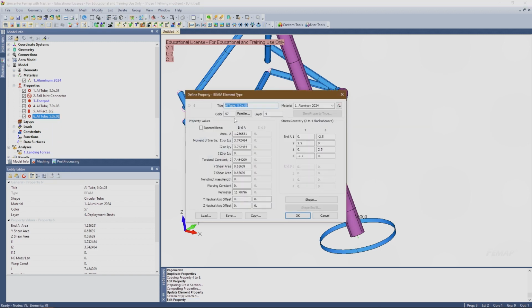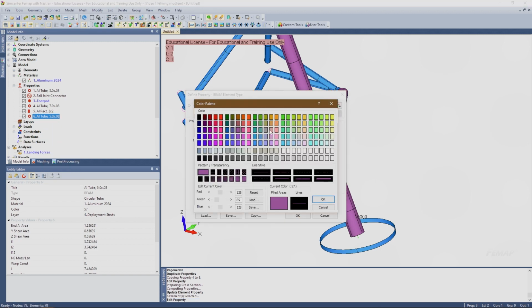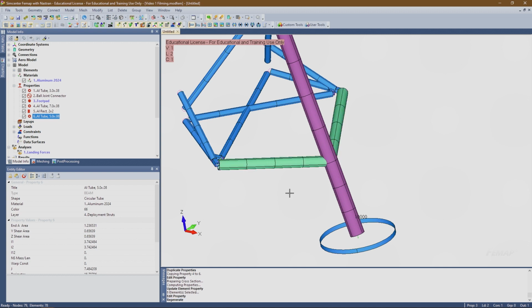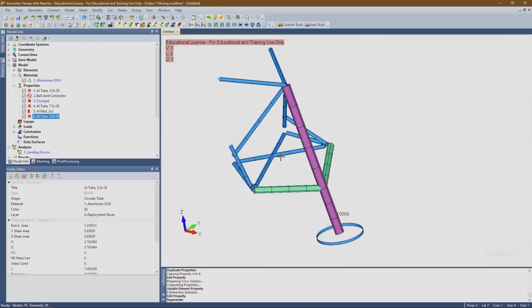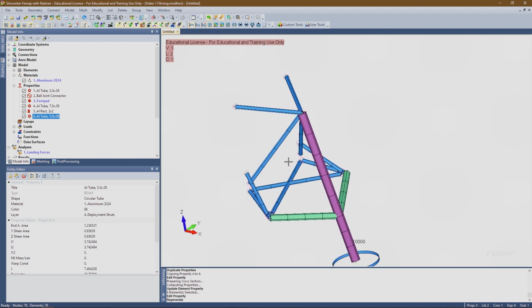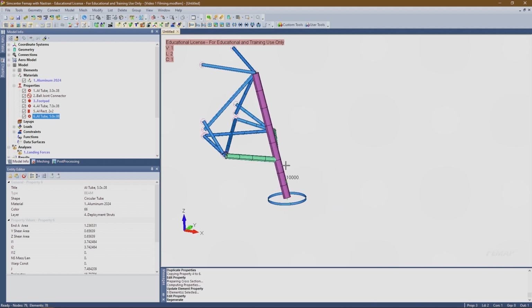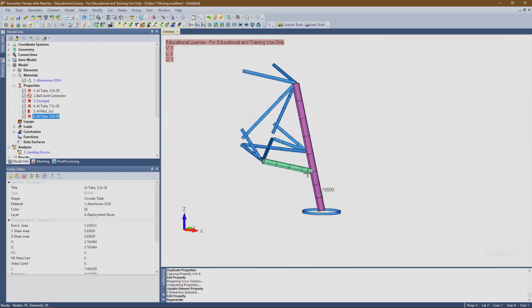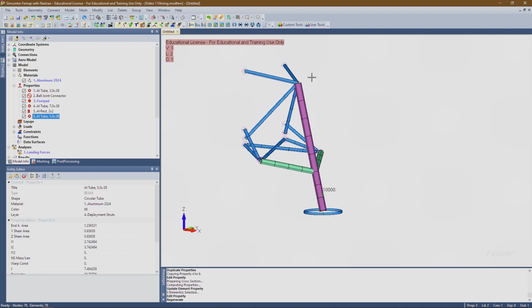Now I also will say, I'm doing this again for fun. There are many ways to analyze things. Not all analysis has to be finite element analysis, right? This structure, even today in 2022, might be easier and better and faster to analyze with hand calculations, using an Excel notebook to calculate all of your strut vectors and your forces on it.